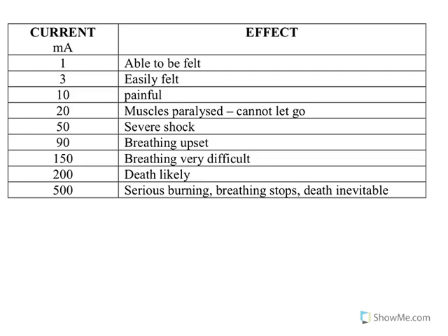This is in milliamps, so it's not much in the way of amps. So all the way from 1 milliamp that you can feel, all the way up to 500 milliamps, which is half an amp, which again could be quite serious.